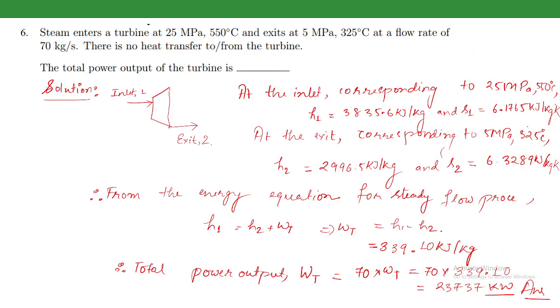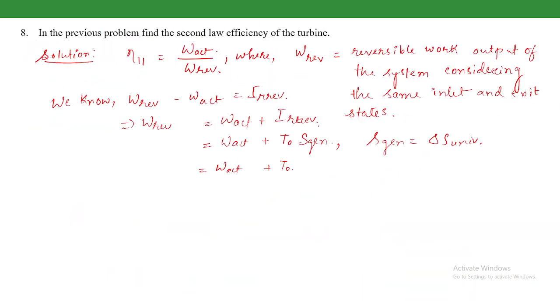So this is a turbine and there is no heat transfer to and from the turbine other than this process, that is the expansion process. There is no heat interaction with its surroundings. So the surrounding entropy change becomes zero. So what is the change in the entropy of the universe? That is the entropy of the system itself, S2 minus S1, plus, if you do this one, there is no heat interaction, so this is zero. Okay, so let me write in the values.